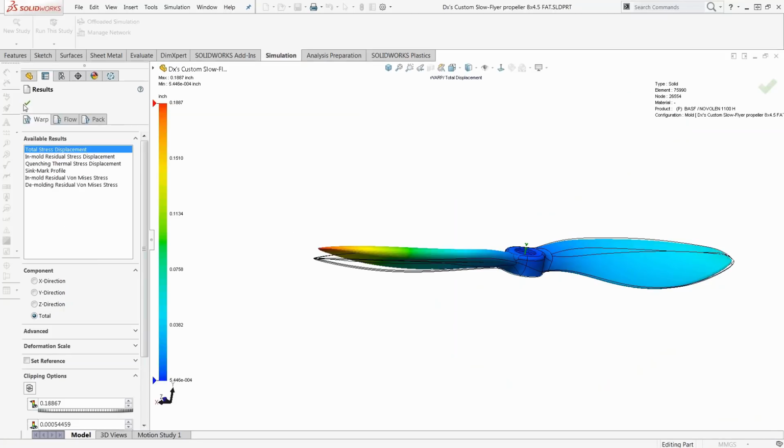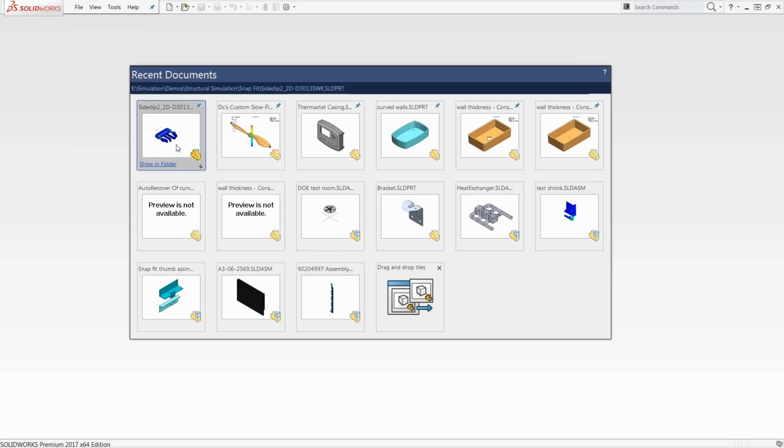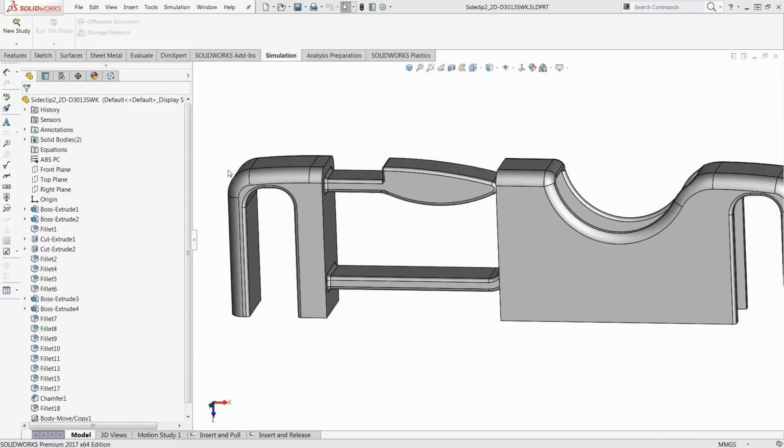In this snap fit buckle example, we want to make sure that we have adequate force to push it down and go into the groove, but not too much force, where a consumer cannot push it down. And if it's too little, then there may be too many high stress areas and it might break off. So we want to make sure we create a good design taking all of these considerations into account.